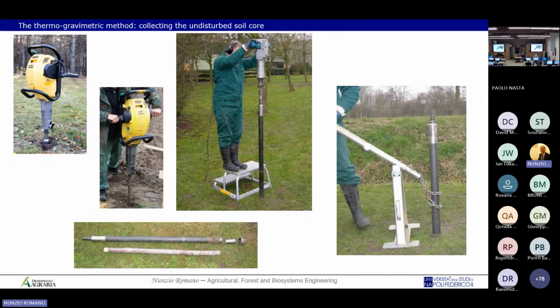This is very useful if you want to collect this core and see the layering of the soil core, and then you can cut the plastic cylinder and test the different parts in the lab.